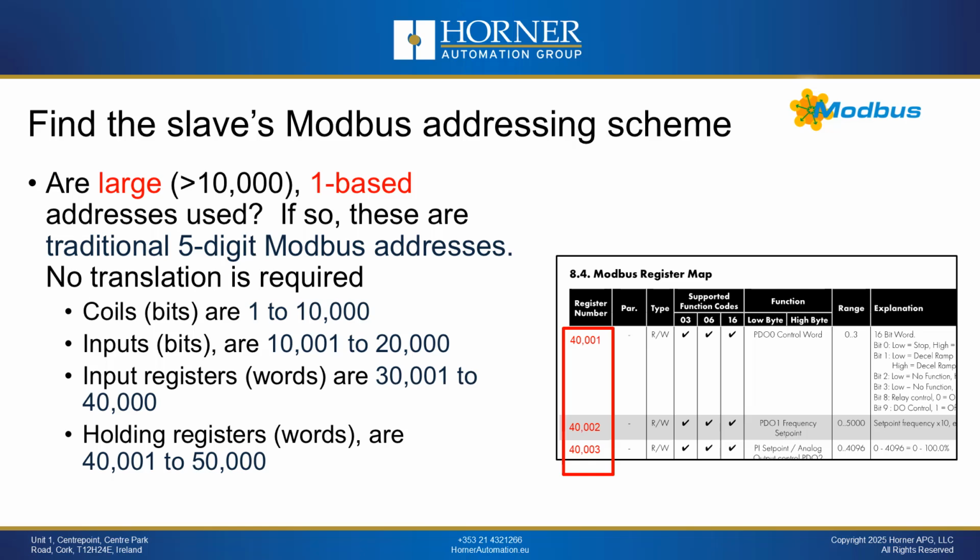Now if we look at the user's guide and we see Modbus addressing listed that looks like what you see on the screen, that means you have got the best possible case. This manufacturer is using traditional 5-digit Modbus addresses, and there is no conversion required. We can just write those addresses down and use them directly.